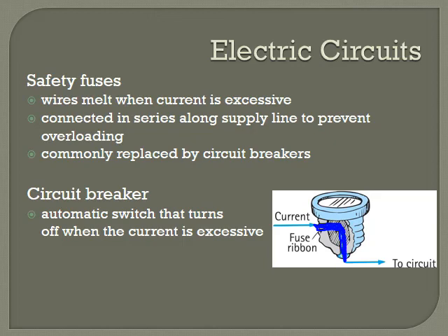this band inside the fuse can eventually, if you run too much current through it, get hot and melt. And when it melts, of course, you're going to have a break in the circuit. When this thing melts, boom. Now you've got a break, you've got an open circuit, current is no longer going to flow. So it's going to serve its purpose. It's going to shut down the current in the circuit and hopefully keep your wires from melting and starting a fire.